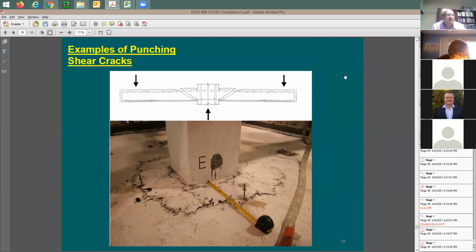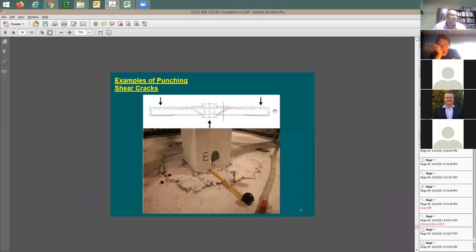And this explains that from this point, which means at the bottom connection between the slab and the column, if you go at 45 degrees, this is going to be the critical section, which is going to be right here, right in the middle. Not here, it's going to be right here, like we're taking an average location.